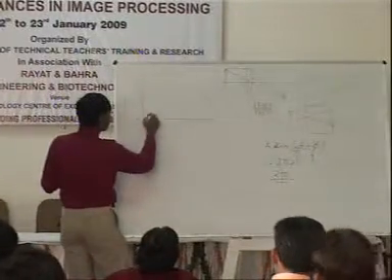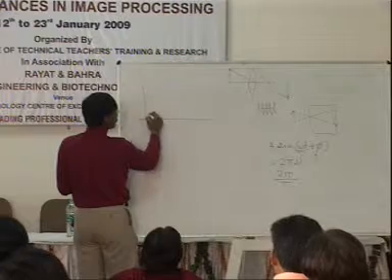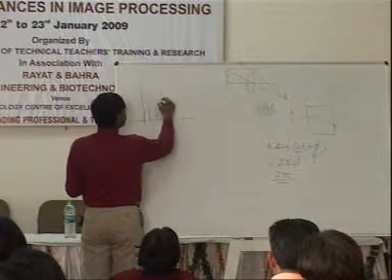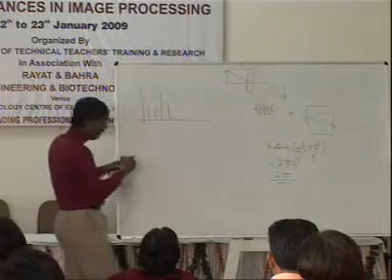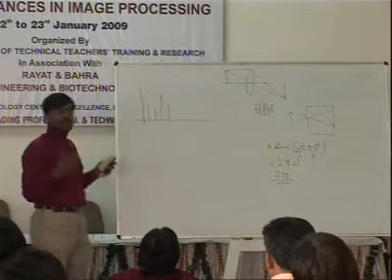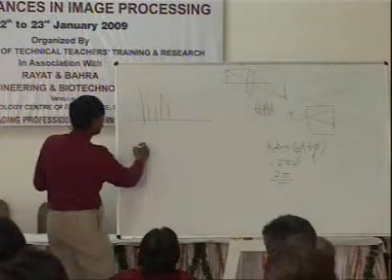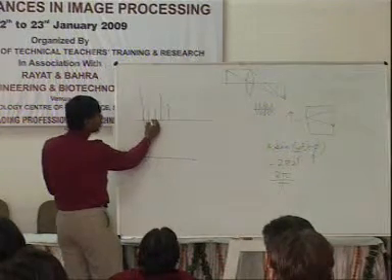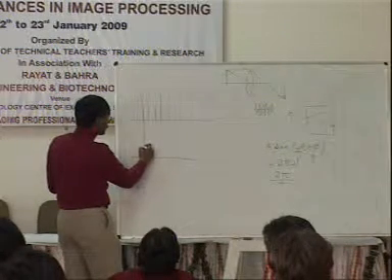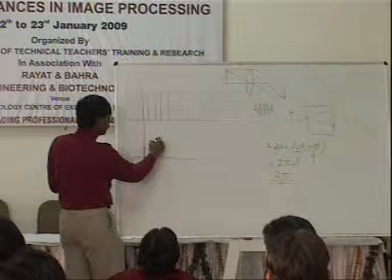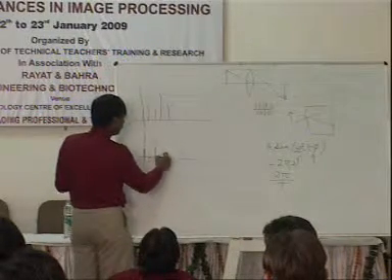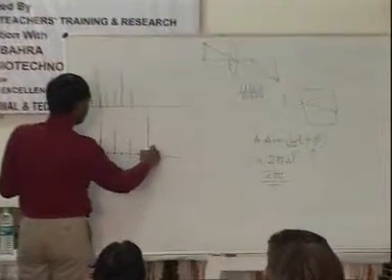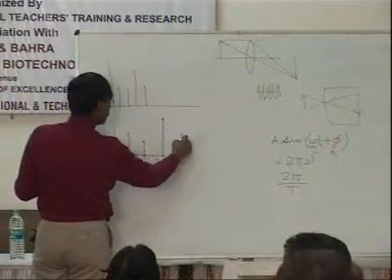The idea is the following. Now, suppose we are given an image or a signal of a particular size. Okay, let's say this is the signal or the image that's given to us. Now, I want an image or signal that is of double the size. So basically, for all of these sampling positions, I want to put in one more sampling position in between every existing sampling position. So here, I have a blank position. After that, I have a filled up one here. I have a blank one here. I have a filled up one here again. I have a blank one, a filled up one here, blank one, and a filled up one over here.